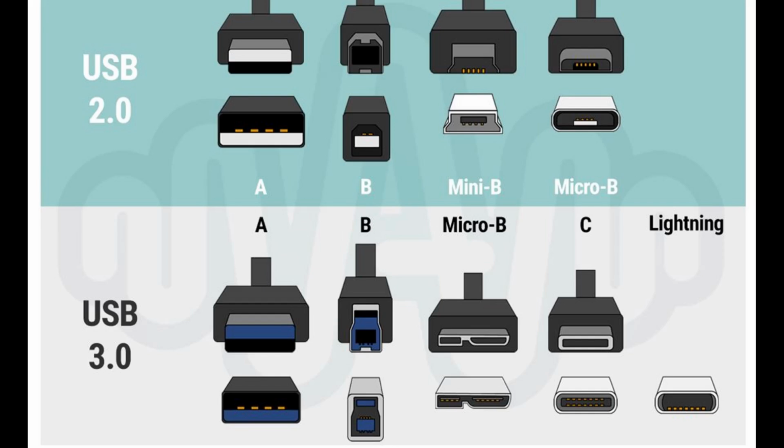USB 1.x. Released in January 1996, USB 1.0 specified signaling rates of 1.5 Mbit/s, low bandwidth or low speed, and 12 Mbit/s, full speed. It did not allow for extension cables, due to timing and power limitations. Few USB devices made it to the market until USB 1.1 was released in August 1998. USB 1.1 was the earliest revision that was widely adopted and led to what Microsoft designated the legacy-free PC.